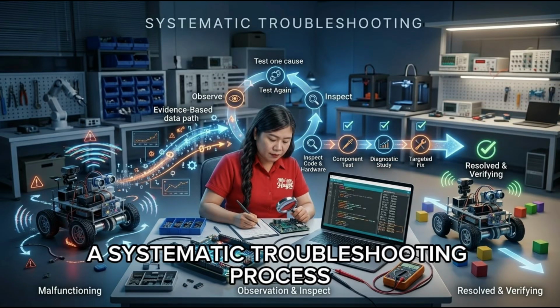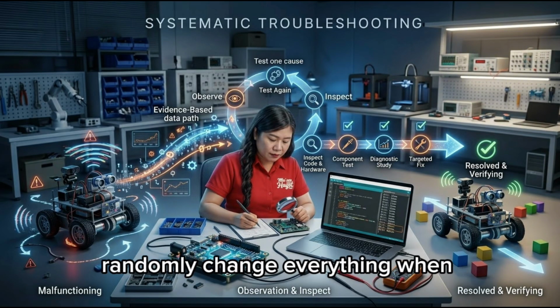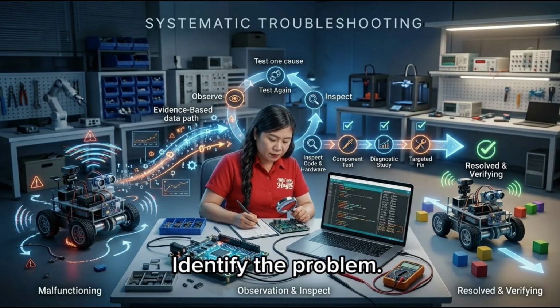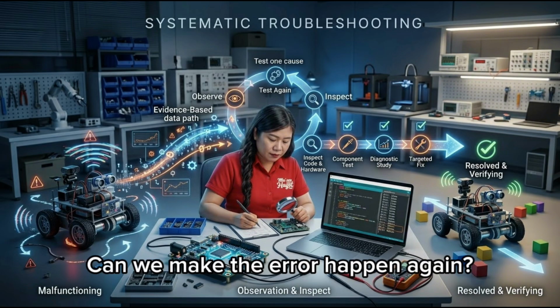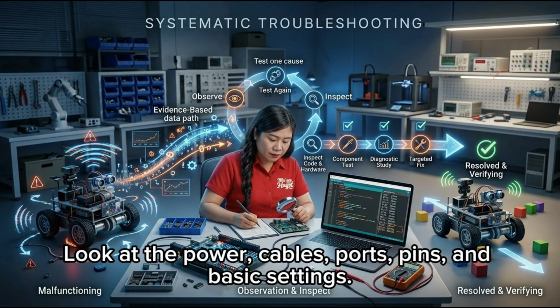A systematic troubleshooting process. A good robotics programmer doesn't randomly change everything when something goes wrong. Instead, troubleshoot systematically. Identify the problem. What exactly is the robot doing or not doing? Reproduce the problem. Can we make the error happen again? Check the simplest possible causes first. Look at the power, cables, ports, pins, and basic settings.